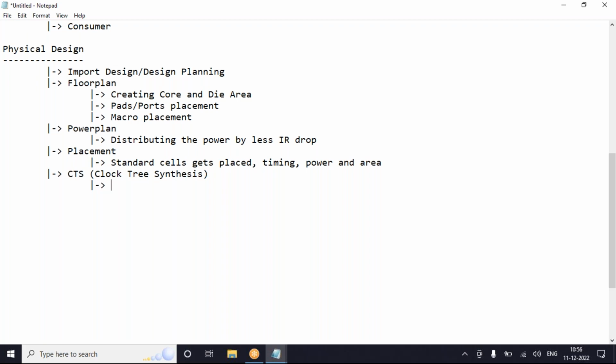right? And also, as you both are getting activated, what about the power? At the same time, if I need to give 2 chapatis, it's not possible, right? One after the other only I can give you. That means with a small time change. So that's why in this particular clock tree building, I have to provide the clock with a minute time difference. I need your friend to be activated after you. Okay, so we will term it as skew.